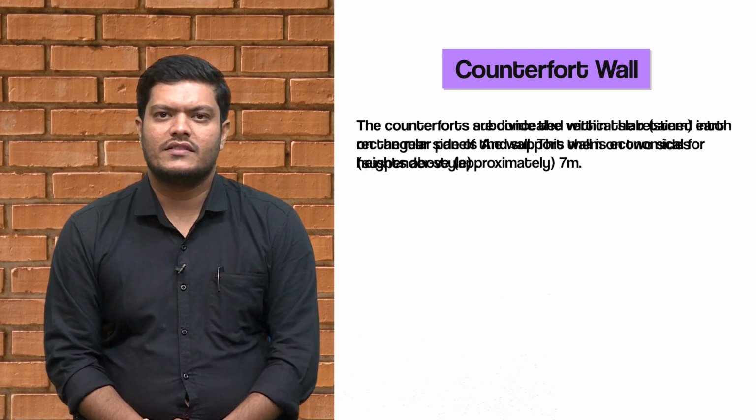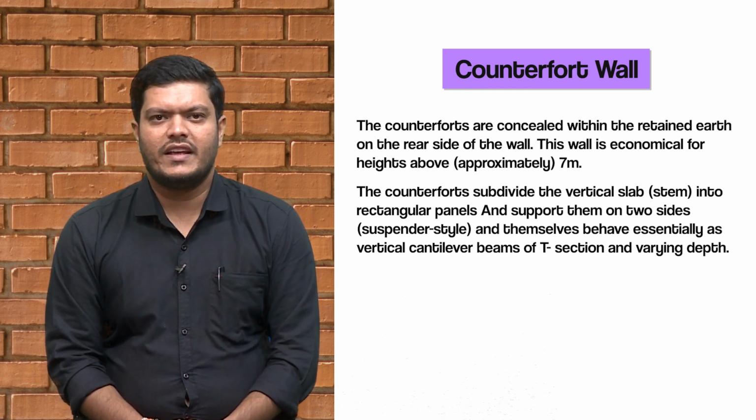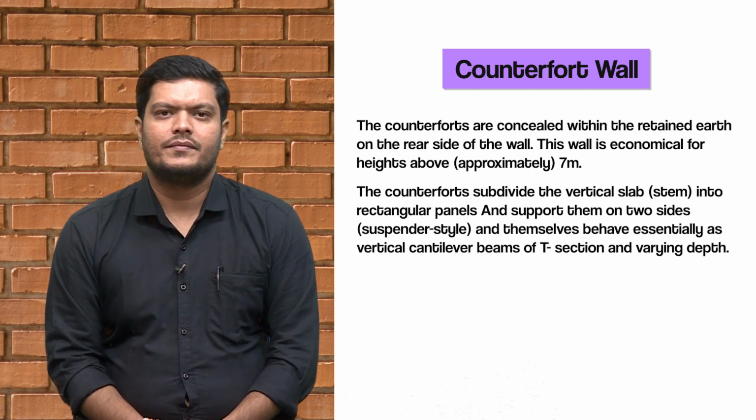The counterforts subdivide the vertical stem slab into rectangular panels and support them on two sides, and themselves behave essentially as vertical cantilever beams of T-section and varying depth.